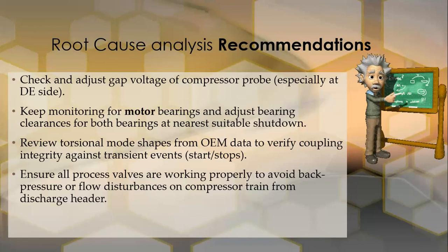So we're going to recheck the suction line composition analysis with a different lab to be sure that there is no liquid entering the compressor. We're going to check the filters of the compressor. We're going to check the mist eliminator of the system to ensure that there is no liquid entering the system.